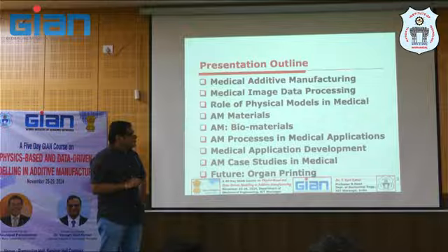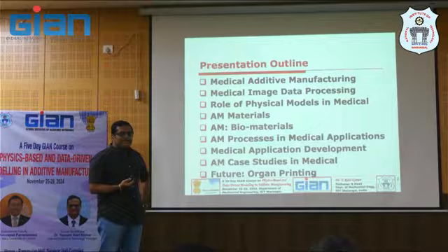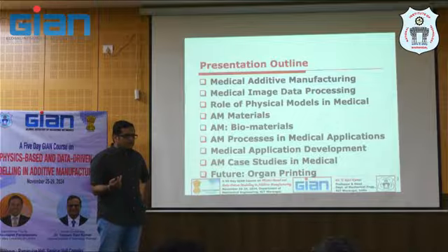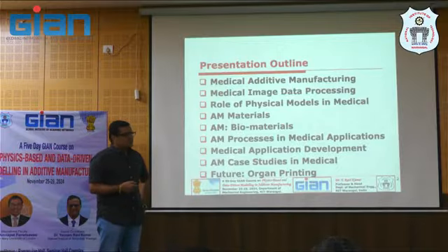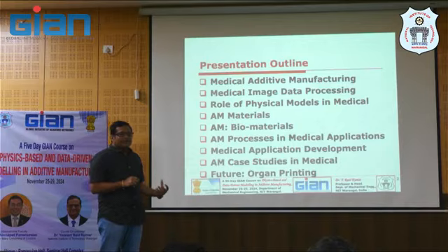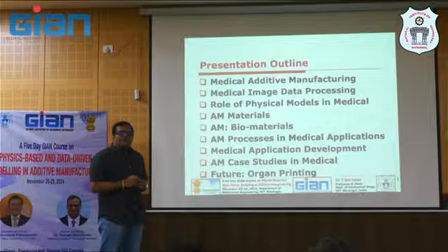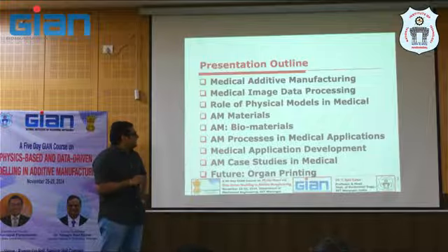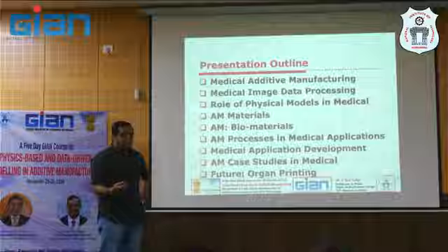And as we know, for additive we need digital data. So digital data in medicine: now, thanks to computers, you have CT and MRI data. The medical image processing is now digital. That is the start point of your medical application of additive manufacturing. You have either CT data, MRI data, ultrasound data, or PET, any scanning modality. DICOM is the one neutral file, so you can get these medical images in DICOM form.